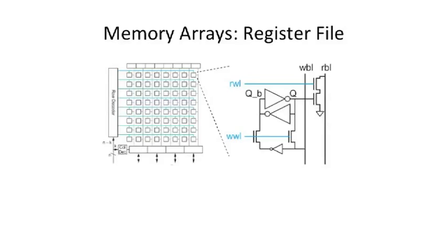In order to have this work, we're going to energize or ground the write bit line such that it's stronger than what either of these inverters can drive. So we overpower the inverter, and we can flip it, let's say, from a 0 to a 1 or a 1 to a 0. So this is not traditional complementary logic, but this is how we typically build register files, small little arrays that are close to a processor.